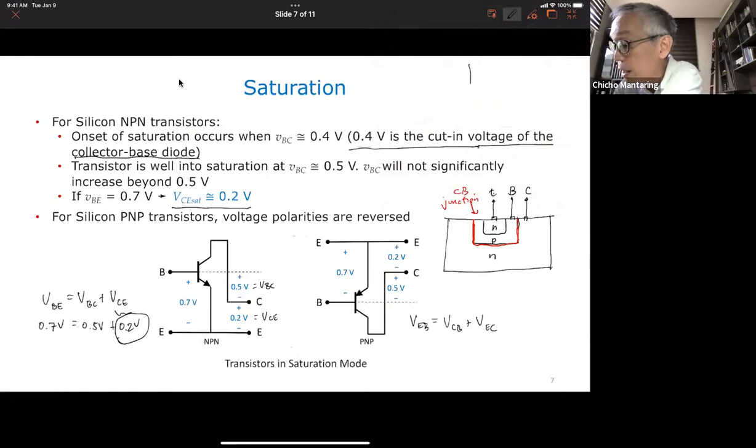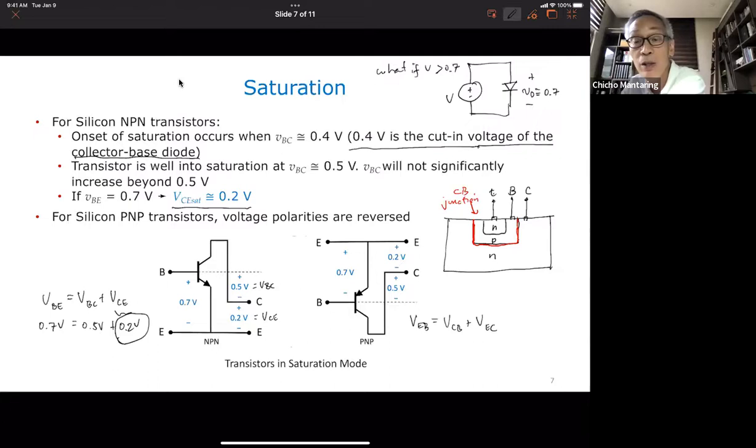So if I have this voltage V, I put this across a diode. So V is forward biasing the diode. If the diode is forward biased, V sub D is approximately equal to 0.7. So what if V is greater than 0.7? From 1 to 3, I just mentioned this is what is considered an invalid circuit. Why? This is greater than 0.7, this is 0.7. So how can you have two voltages in parallel of different values?